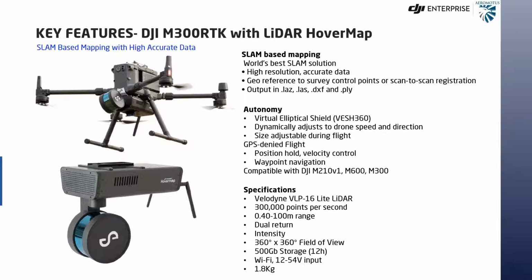It's got a 360 by 360 field of view, which helps us capture the site without any obstructions compared to ground-based LiDARs. You have 500 GB of storage, which will give you 12 hours of data collection. Wi-Fi enabled, with 1.8 kilometer range.